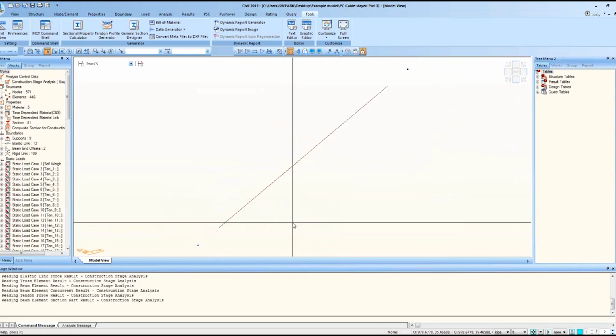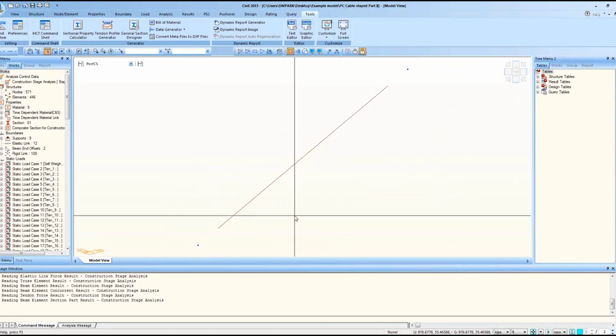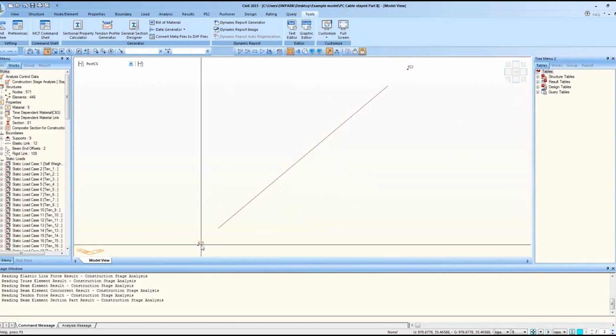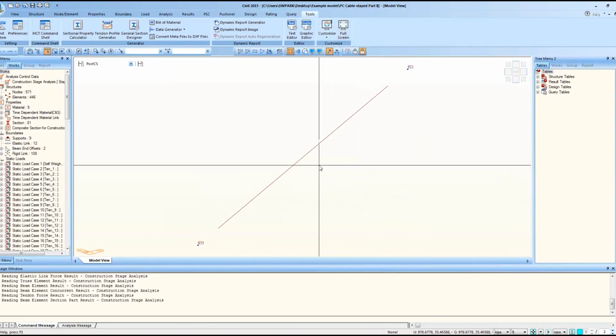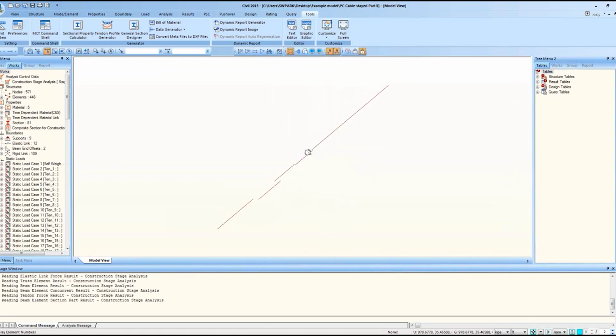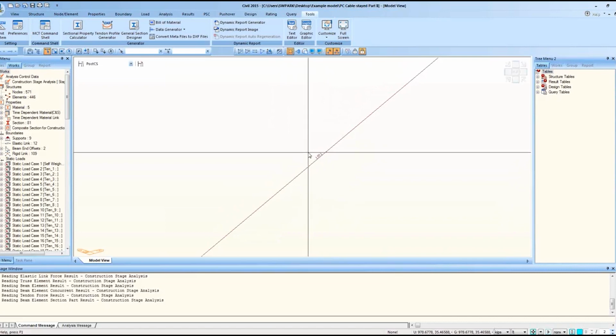And also here, if you want to see the node number and element number, turn on this button, Display node numbers. It says 853 and 921. And if you also want to check the element number, turn on this button. This one says 1501.